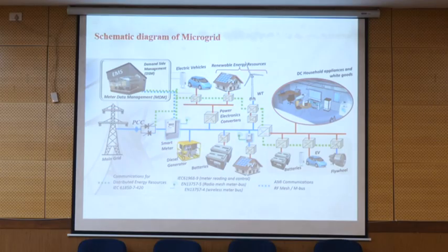But the difference from the grid forming converter is that this converter is following the reference based on the grid. So if grid is disconnected, but the frequency was 50, it has information that the frequency is 50. Okay, but in grid forming, you can form it. You can say that the frequency is 70, 60, I don't know, 40. You can decide based on the demand.